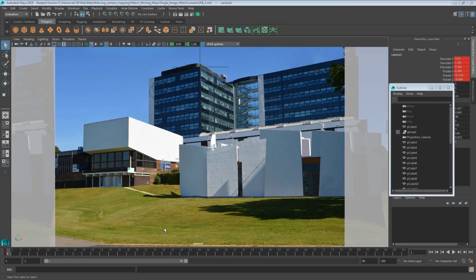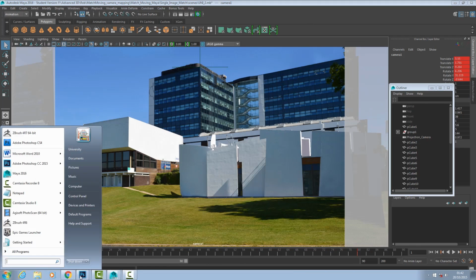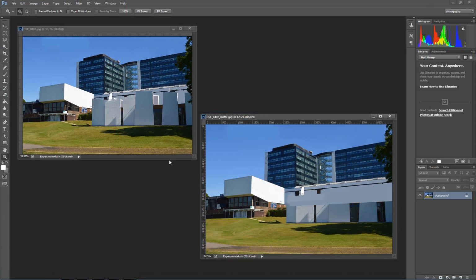So the easiest way to do this is to create two different images, one being the original one, which is this, which is completely fine, and one that has been modified to reduce assets being projected onto the wrong pieces of geometry. In this instance, I've taken the top section and removed everything. So the only part of all the models that this entire photograph will get mapped to is this section of the building. To do this, we need to create another shader.